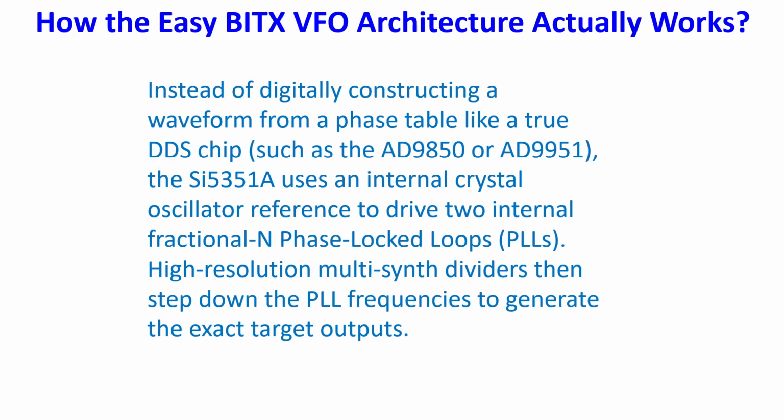Instead of digitally constructing a waveform from a phase table like a true DDS chip such as the AD9850 or AD9951, the SI5351A uses an internal crystal oscillator reference to drive two internal fractional phase-locked loops, PLLs. High-resolution multi-synth dividers then step down the PLL frequencies to generate the exact target outputs.